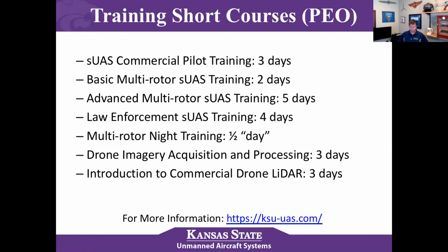I would like to ask about the slide concerning RTK versus PPK. Sure. You're saying PPK is better for actors. Yes, I am. When we do our clouds and take them against about 6 to 10 ground control points, I am seeing RTK as not as accurate on LiDAR systems of the same IMU.